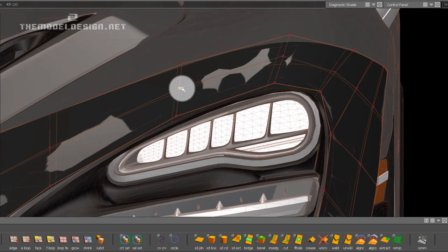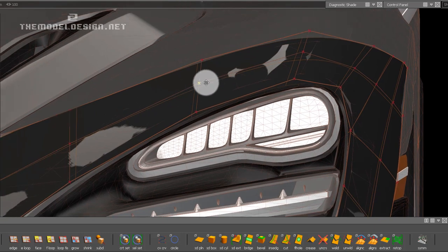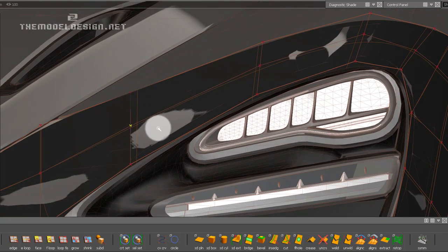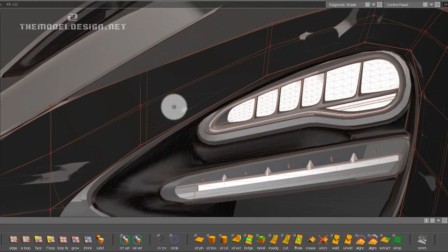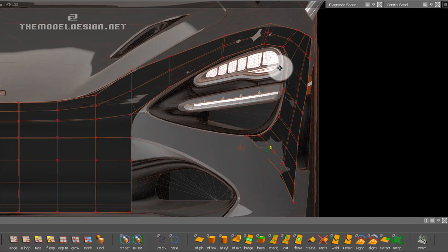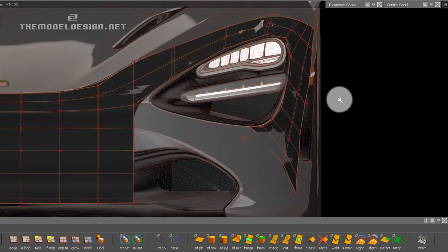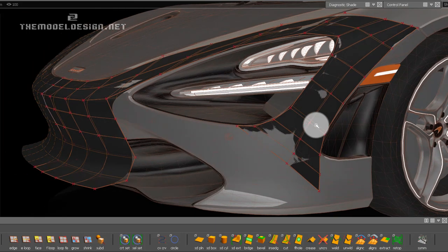You can give it just a touch of curvature in here. Otherwise we will end up with a surface that is really too flat. Now one more look at the CVs, and I can see that there's a lot of wobbliness going on.